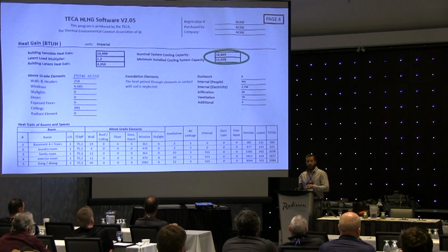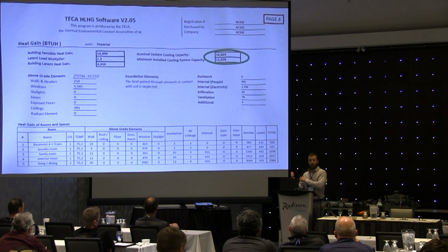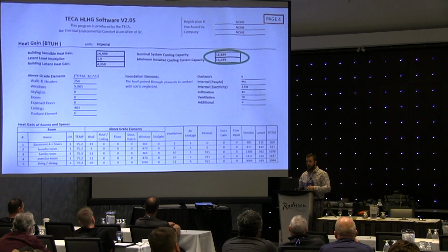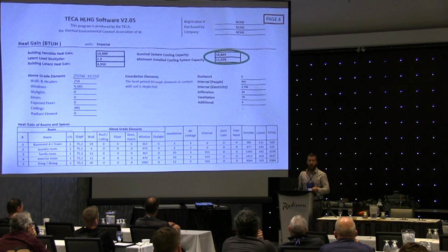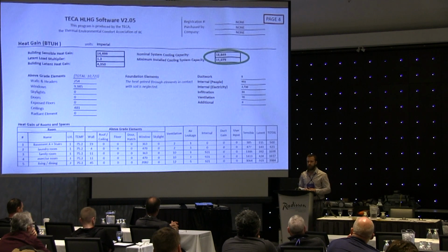We're considering worst case scenario, right? I need to be able to cool this room at worst case scenario, which is when it's full of people and all the appliances are going and producing a ton of heat. I still need to cool that room. Worst case scenario for heating, though, in the cold season, the winter, right? If I have a whole bunch of people in the room and I'm operating the stove and everything, well, that's actually helping the mechanical system, right? Worst case scenario is when it's just me down there at 1 a.m. eating cereal. I still need to properly heat that room when there's no internal loads. So worst case scenario is when it's empty. That's why we consider internal loads for cooling, air conditioning, but not for heating.